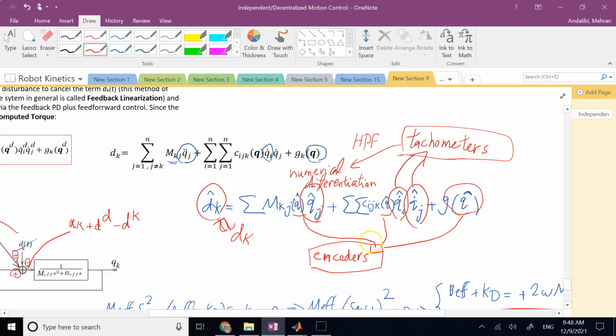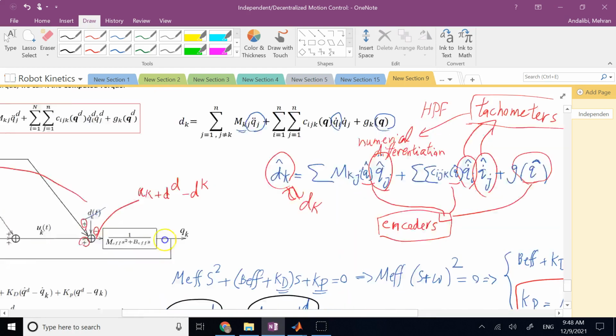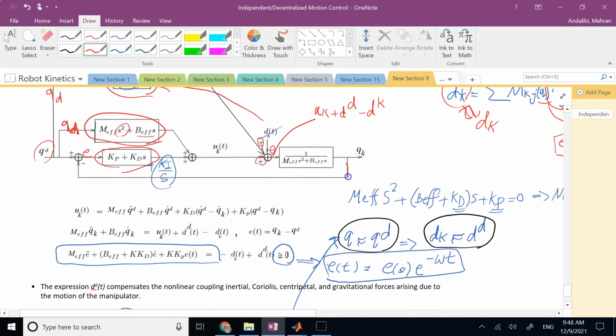Not all of the measurements from the sensors, especially tachometers and encoders, come without delays. They always have a delay in the feedback line. So if instead of this q, you now also have to get what? Some q dots and send them all in to this brain, the controller, that gives you back what? q hat and q dot hat, and then q double dot hats.